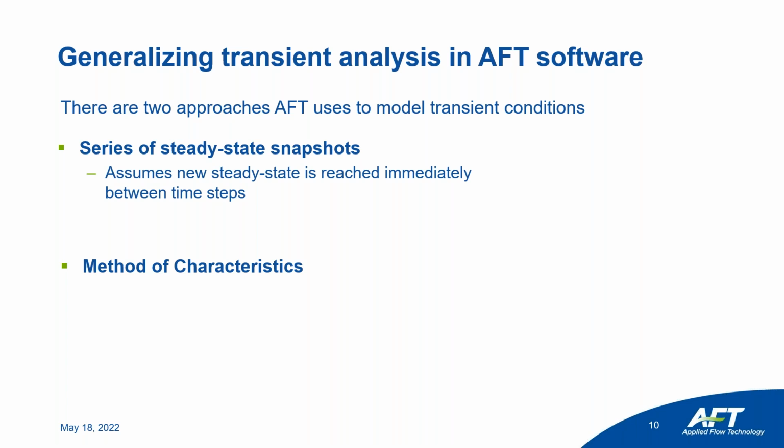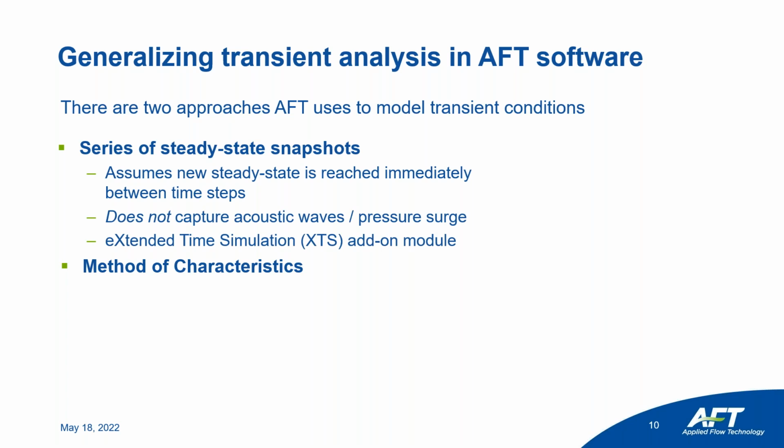In the case of Arrow XTS and also Fathom XTS, there's no heat transfer, and it's not going to capture those acoustic waves or pressure surge. This is again what we call the extended time simulation add-on module, where we're building on the steady state solvers of Fathom and Arrow to capture these transient changes over time.